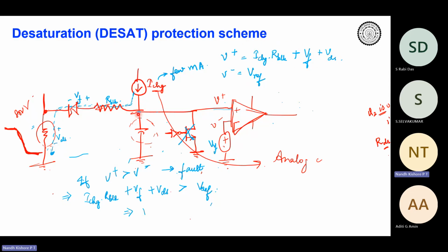So the voltage over here is clamped, which means that even if you now connect the capacitor, the capacitor would simply charge up to this voltage and that's it. The capacitor is now holding a DC voltage, and obviously you know that the capacitor will not allow a DC current to flow through it if the voltage is clamped. Now it acts like an open circuit.